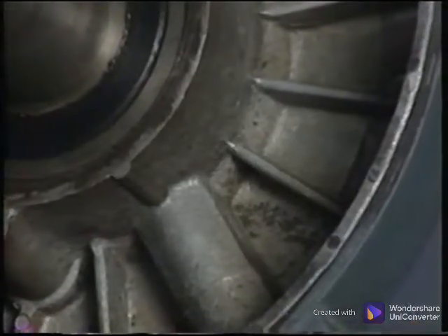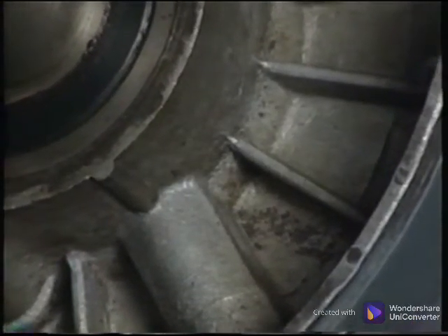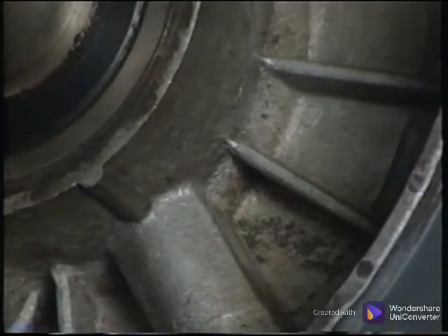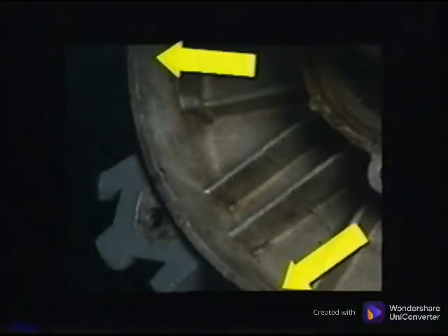The cover on the inboard end of this motor has reinforcing vanes molded into the casting. These will transmit energy from the bearing location to the sensor with little loss. However, the places without the reinforcing vanes are voids, and the energy is not transmitted as well to these locations.